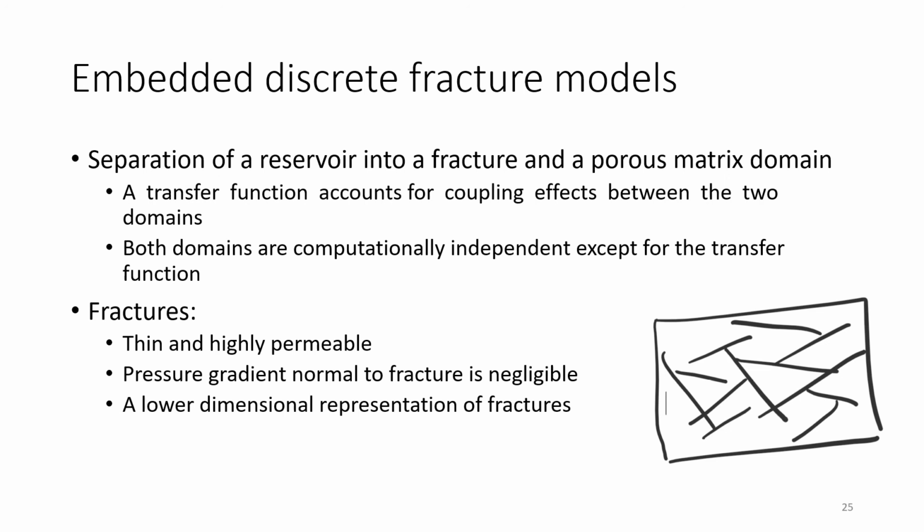here you have this geometric reduction of fractures, right? So in a 2D space, 2D plane considered here, then you have your fractures as lines, right, with a start and end point and some kind of maybe aperture from which you then can calculate porosity and hydraulic conductivity. But this is reduced in the spatial dimension. All right.